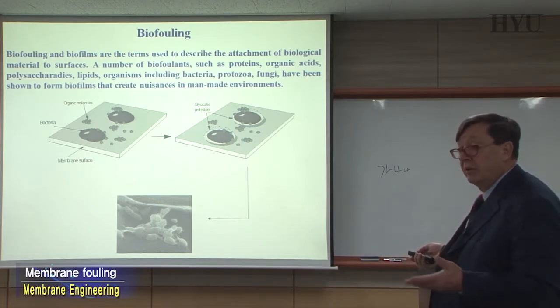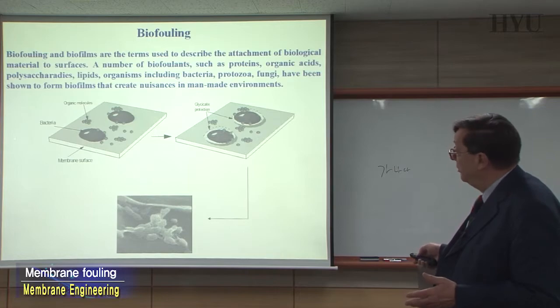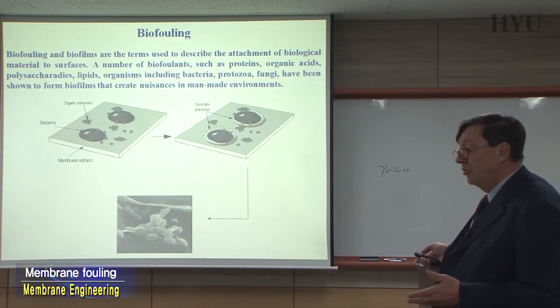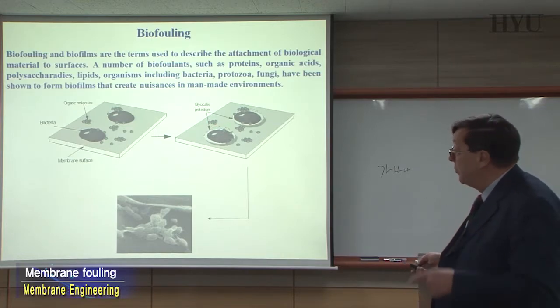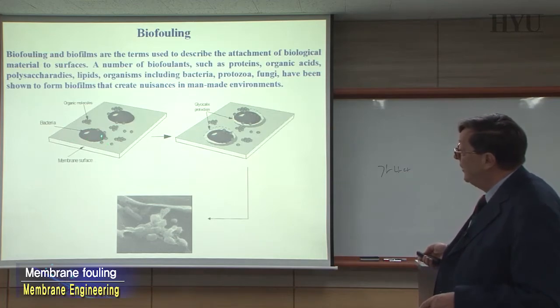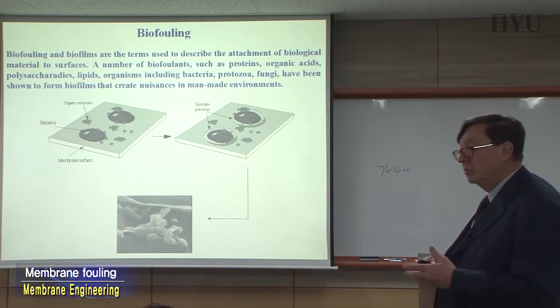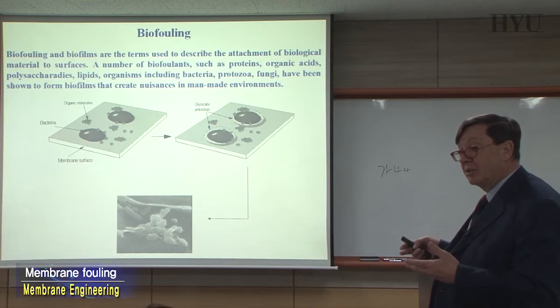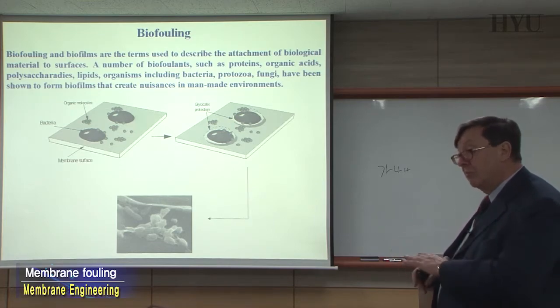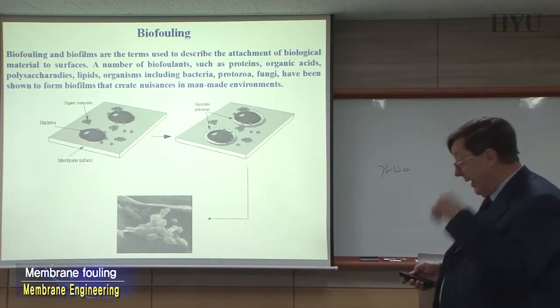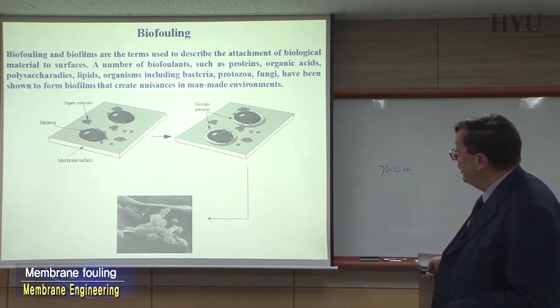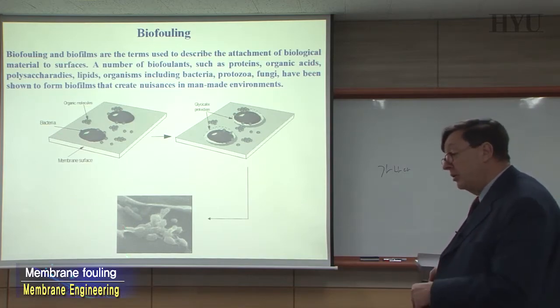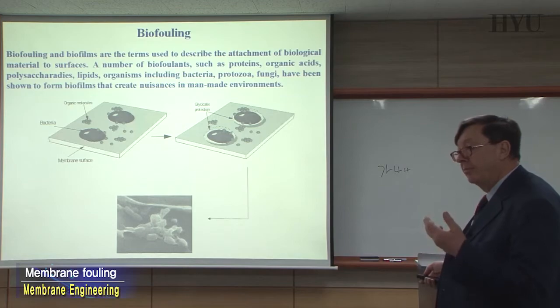Change in thickness, no change in thickness, because it's single particles. So no real problem. The real problem is when these particles, if they have some nutrients around, start to grow, to interact with each other, and to form some homogeneous film, and eventually they penetrate in the pore. And when they penetrate in the pore, there's no way to remove them.